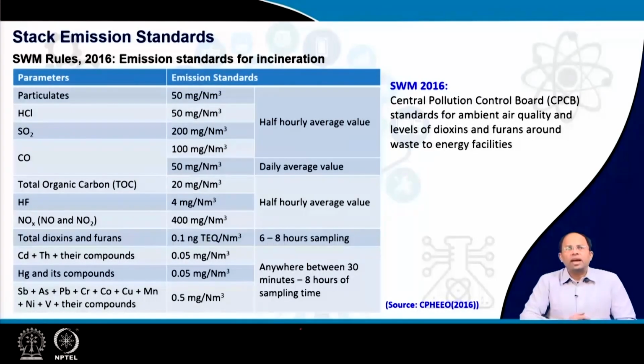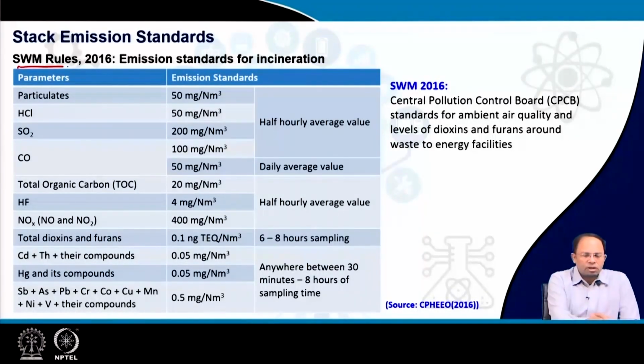So coming to the final emission standards as given in the Solid Waste Management Rules, you can see that we have got emission standards for particulate matter, which is 50 milligrams per normal cubic meter, HCl, hydrogen chloride 50 milligrams, sulfur dioxide, carbon monoxide, total organic carbon, hydrogen fluoride, NOx, total dioxins and furans and so on.